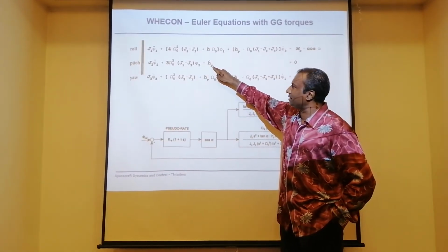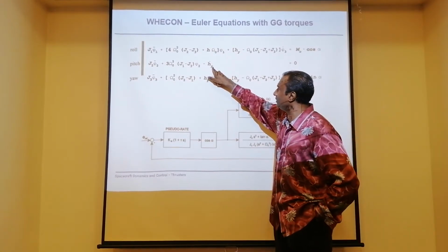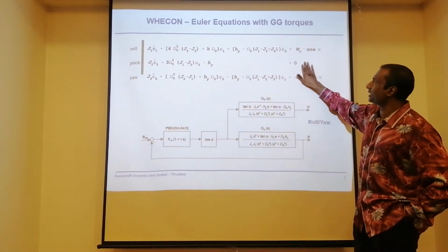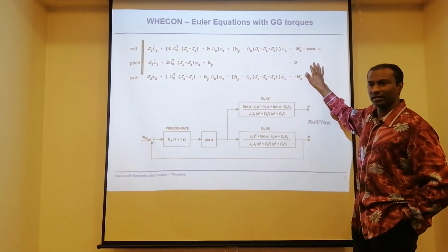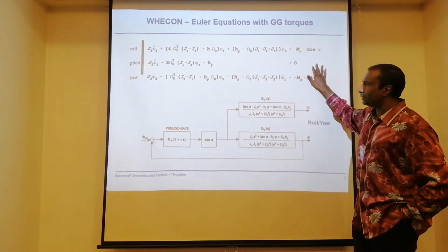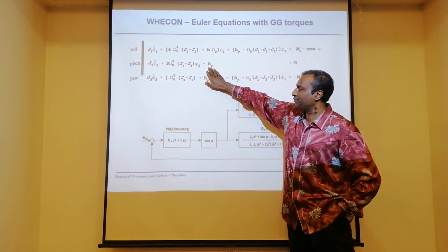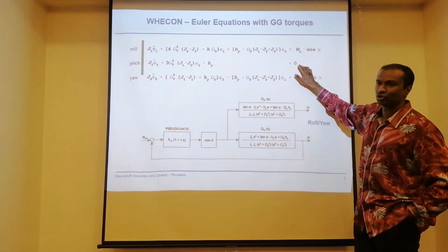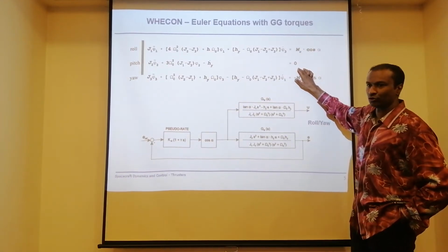That means if I increase the speed of that momentum wheel, I should be able to have a torque. Okay, again, remember all those disturbances will be on your right side. So there is a disturbance here actually. I didn't write it, but you will have those exact disturbances. Okay. So let's say I move that pitch axis. Let's say I move this control torque here. Here will be plus H dot, and this is a torque. So this is an internal control torque.